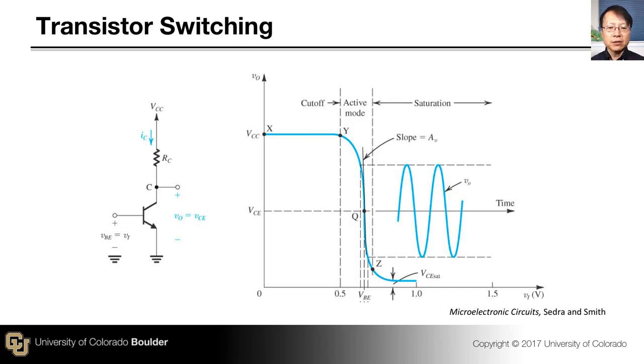So here is a very simple circuit involving a bipolar junction transistor. This configuration is called the common emitter configuration. The emitter terminal is on ground, your input voltage is fed into the base terminal, and the output voltage is taken off of the collector terminal, which is connected to a load and eventually to a power supply.